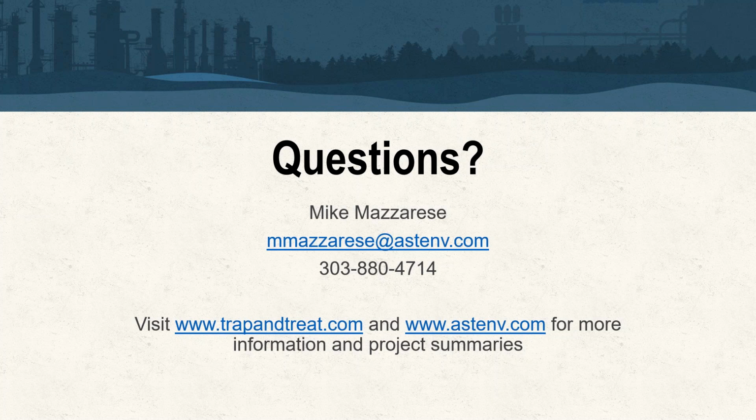In that case, I've seen sites where that has happened. But with slurry injections, the volumes are relatively low. So we didn't see on that site, or really on most of the sites I work on, where we've displaced contaminants and pushed them outside of the treatment area. Does that answer the question, Bill, do you think?